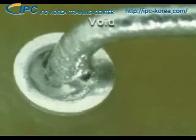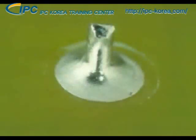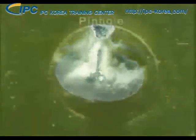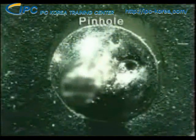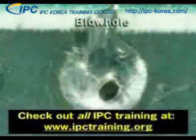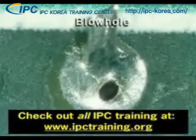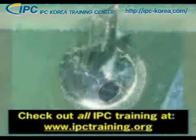A void is an open area caused by air trapped within the solder joint. This is an allowable condition as long as the solder joint meets all of the other dimensional requirements. Voids are process indicators. Pinholes and blowholes are also examples of process indicators. Blowholes are larger than pinholes. They are created when heated gas escapes from inside the solder joint.